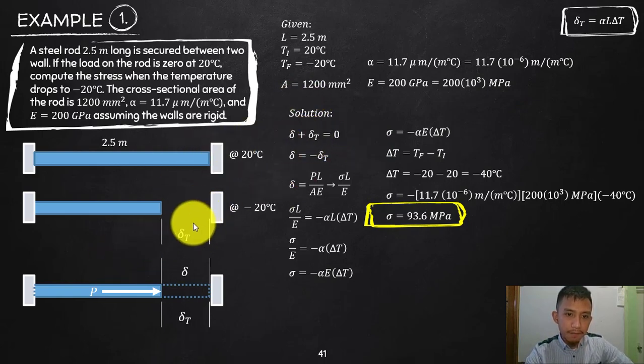Look at this. The deformation due to temperature is this one, but that will be brought back, that will be cancelled due to the stress that is being experienced. And that is true because there will be a stress that will return that back, because that supposedly is to be still attached, that is restricted. So whatever is experienced, that will always be restricted. So there will actually be no change in length. That is just for us to symbolize the effect of the temperature. But actually this will not happen. It will not leave a gap, or it will not leave the wall.